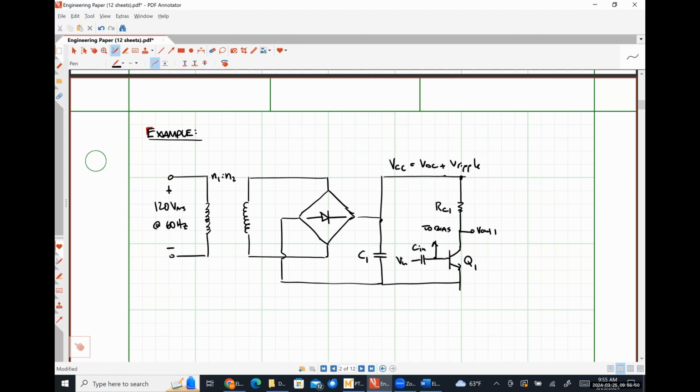So what would we expect to see here on our output voltage? We're going to see some noise. We're going to see some distortion because of the power supply ripple, right? So how might we convert this single-ended amplifier into a differential amplifier? Well, what we're going to do is add another common emitter amplifier, where this resistor RC2 needs to be matched to RC1.